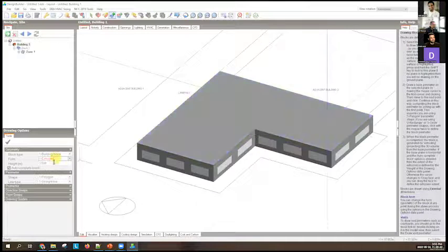And the thing that I could have changed is the height of this block. At this point, it's 3.5 meters. And you can see that there is a building up. The building has some default windows and some default constructions, and we call this a kind of garbage in, garbage out model, because I don't know any of the inputs clearly unless I've set up the default numbers.